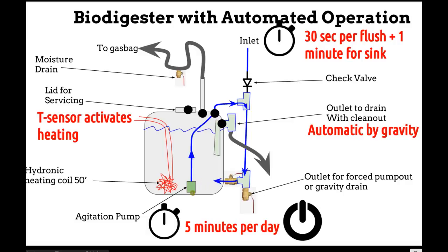you agitate the digester by pumping actively in a circuit like this that breaks apart any surface scum. It agitates everything so there's no dead spots. Everything is alive and active. Because one of the things you can get in a biodigester is, for example, oil films on the top that totally cake up, and everything gets, it's like an iceberg on top, and activity might stop if you're not mixing things. So you do an automated mixing system.